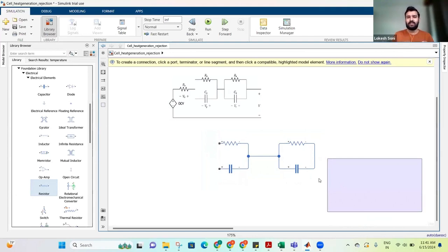RC modeling basically is, you take a battery or a cell, you draw current from it. What you see is there is current given by the cell, and there is some sort of voltage behavior at the cell's terminal. All you want to do is mimic this voltage behavior, how the current is taken out from the cell and how the thermals are working in the cell.